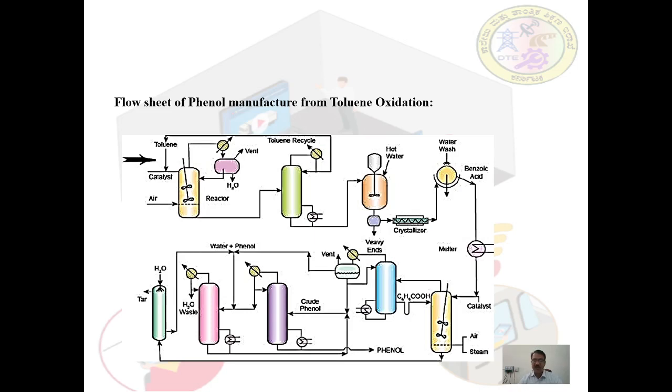The phenol water coming from the three different sources is allowed to enter the distillation column that generates water waste as a top product and the crude phenol stream as a bottom product. This is the process taking place in the production of phenol by two-stage oxidation.